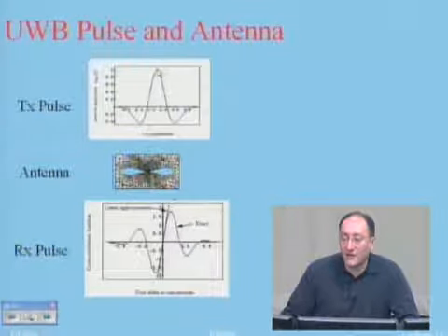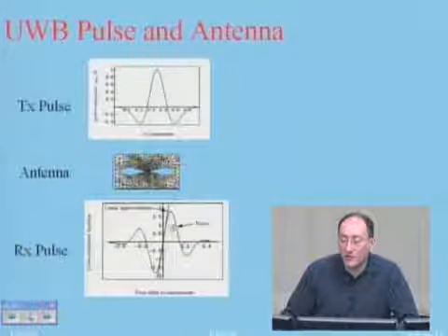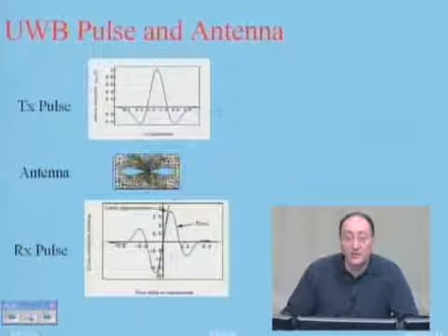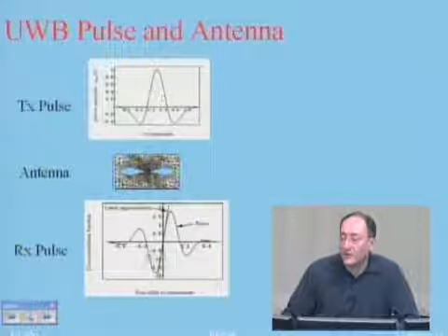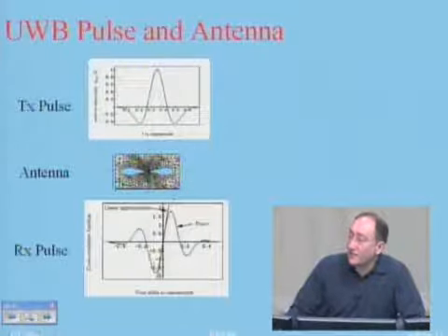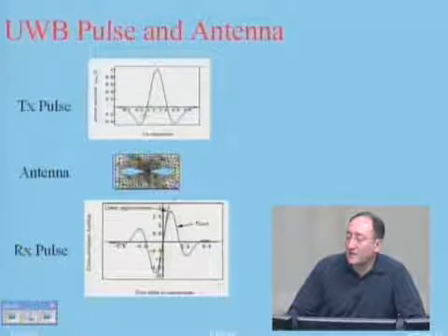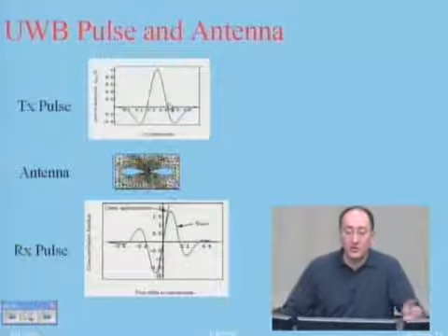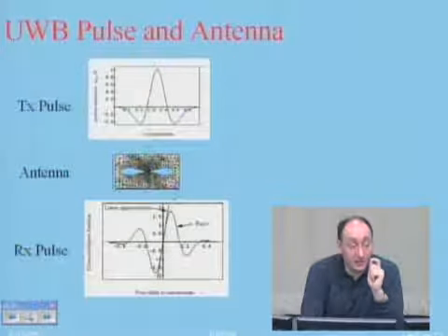See, whenever this one is flat, it's 0. Then when it's moving fast, it goes up. Then in here, it comes up. So this is really the derivative of this pulse. But anyway, this is still a pulse. The shape is like this, rather than like this. And that's how they do the ultra-wideband communication, the original, which is impulse radio.